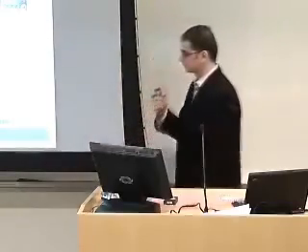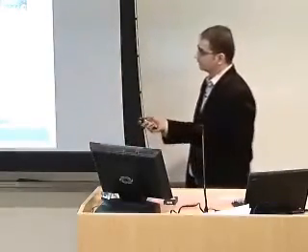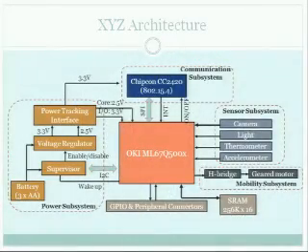Now, the second platform I'm going to use is the mPlatform architecture that we designed here at Microsoft Research. And this architecture basically enables putting together in a single node application stack several different heterogeneous processors as well as several different heterogeneous radios, right? And in this case, there are several trade-offs that come on at the hardware level on how you interface these things together. How do you enable communications of these different processors and radios on the same stack to get an energy-efficient sensor node? But before I go into this more complex case, let me first focus on the single processor case where you have the XYZ.